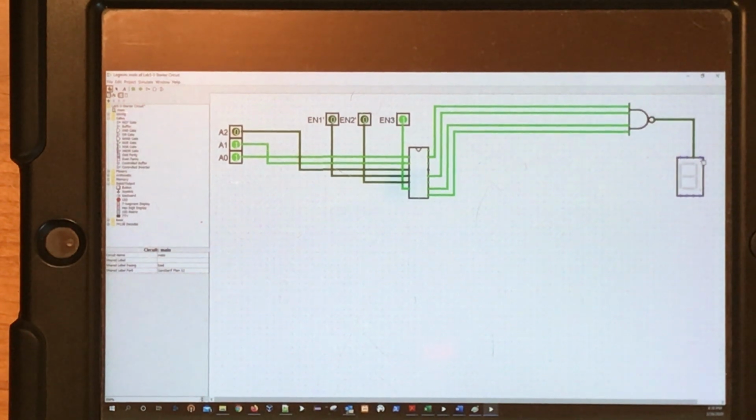So I'm confident now that it matches with my truth table. I'm reading it from top to bottom. I had it from left to right. This decoder is weird the way it uses C as the most significant bit, so I wired things up a little bit strangely. Just keep track of that. I got to pay attention to details and notice when something's going wrong. All right, B. 0, 4, 5, 6, 7. Oh, wait. One other thing to do here.